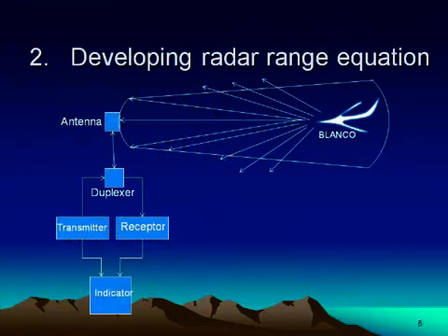The whole radar operation is shown in the block diagram here. So just to recapitulate, we are first transmitting the signal through an antenna towards the incoming target. As the waves propagate, they get expanded, so the power available at a particular point will get reduced. So at the location of the target, the power density is going to be very much less if the target is too far.